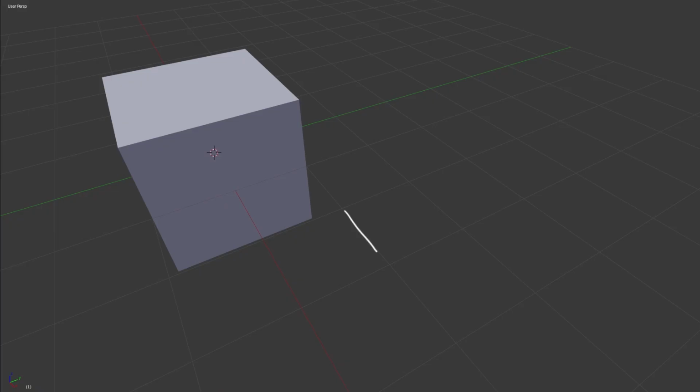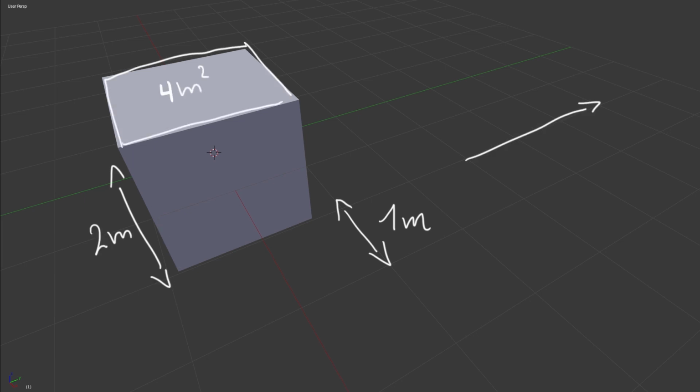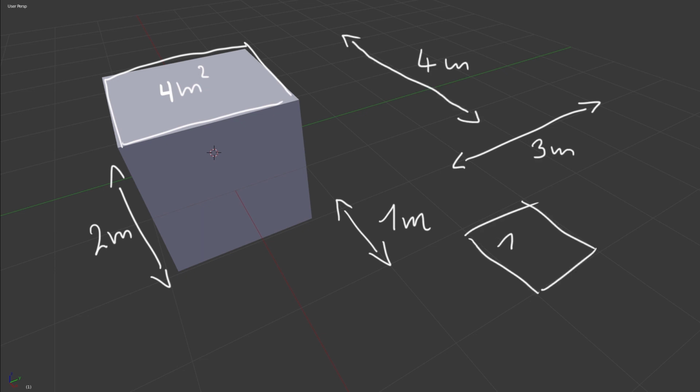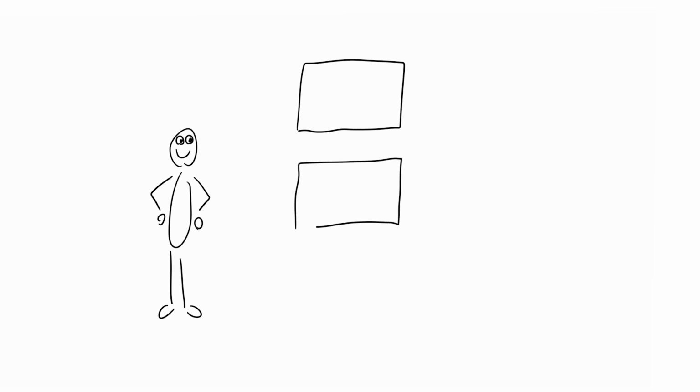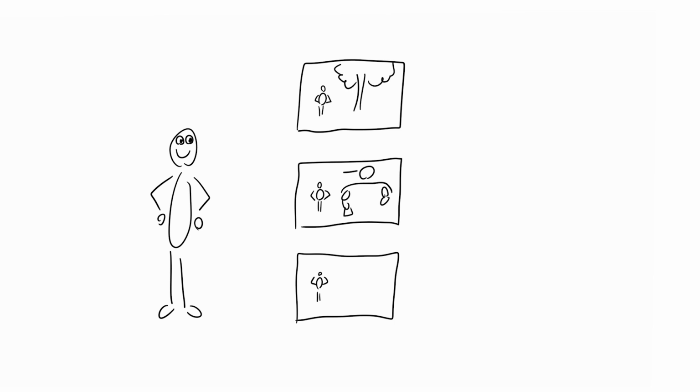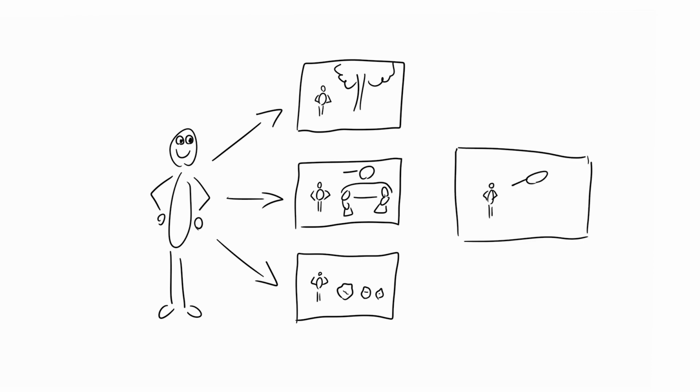But to keep it simple, we can say one Blender unit is 1 meter in our scene. That means the grid inside Blender is a very good orientation for us. Another way to ensure a consistent measure is to create a reference object. For example, a rough shape of a 3D character, which represents the size of a human being. And this we can simply copy and paste with Ctrl-C and Ctrl-V into our different assets files, and then we can create all the objects in relation to this reference object. And then if we link everything in our main scene, the proportion will fit together.